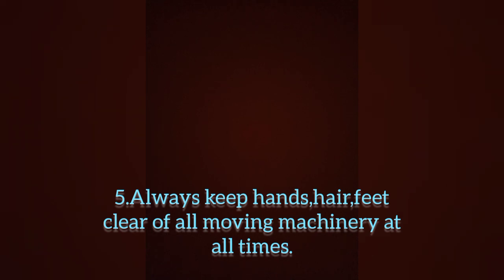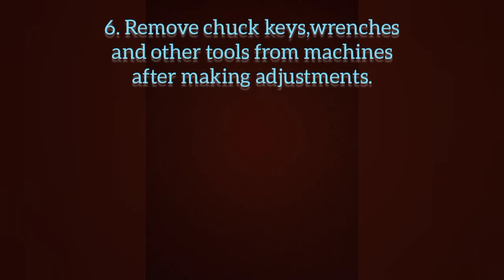Be aware of all moving parts, especially the cutting tools and the chucks. Remove chuck keys, wrenches, and other tools from machines after making adjustments. Listen to the machines. If something does not sound right, shut it down. If the machine sounds abnormal to you, it probably is not operating properly, so inform the shop monitor of the problem.